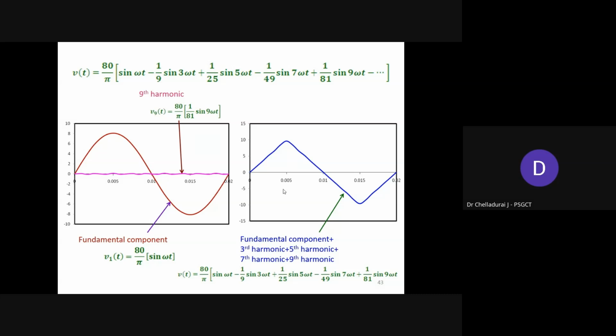So in power electronic converters, while converting or controlling the positive set of devices and negative set of devices, if we get a symmetrical firing pattern, or a symmetrical nature of the positive set of voltages and negative set of voltages, then totally we can eliminate the even order harmonics.